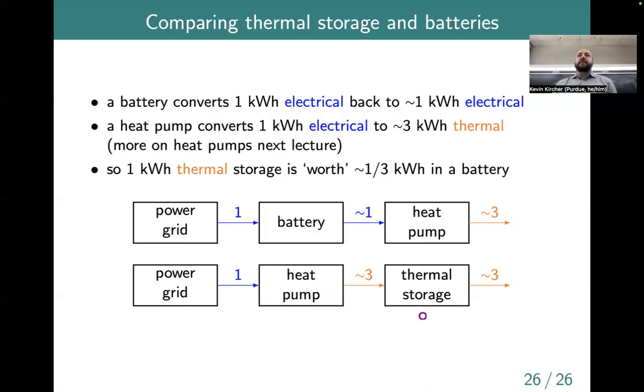Yes. What's the self-dissipation of the battery versus the thermal storage? Because that might affect this. Again, we'll talk about thermal storage next week, but the question is, what is the self-dissipation of the thermal storage? And it basically has to do with heat losses. So suppose that we were storing heat in a big water tank inside this room. Then the self-dissipation of the energy stored in the water tank would just be conduction through the tank wall to warm up the ambient air around it. Water heaters do bleed a little bit of heat. If it's in a cold basement, it'll lose a little bit of heat over time. But the more insulated the tank is, the less that effect is.